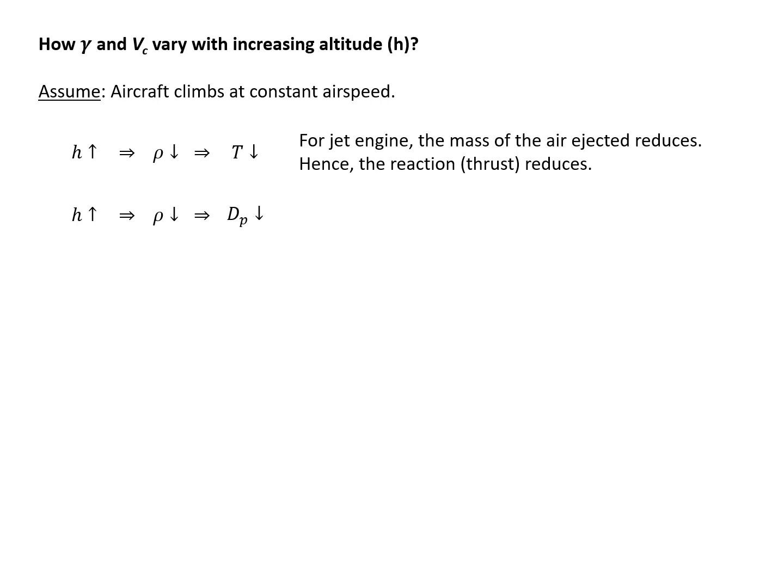Okay, and similarly, with increasing altitude, density decreases, and the parasitic drag reduces. This is because Dp, parasitic drag, is calculated as half rho V squared times S times CDp. And we can notice CDp has a dot on top of it. So the parasitic drag coefficient is a constant. V doesn't change, S doesn't change, but the density changes, so Dp is reduced.